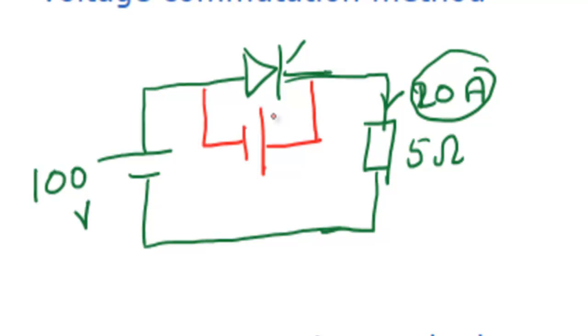Generally in electrical circuits, whether this is 1 volt or 100 volts doesn't matter. Why it doesn't matter: the voltage suddenly applied across the device will have more impact than the source voltage, because it is directly impacting the device. Even though the source is 1000 volts and this is 1 volt, it doesn't matter, this thyristor is reverse biased. So that is what we are discussing here.